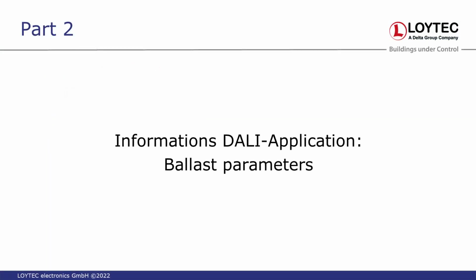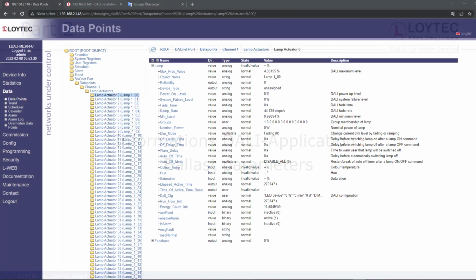Information about the DALI application, ballast parameters. Along with the short address, the group assignment, the scene configuration, DALI ballasts store the following parameters: the max level value, which is the max dim level assigned to that ballast,